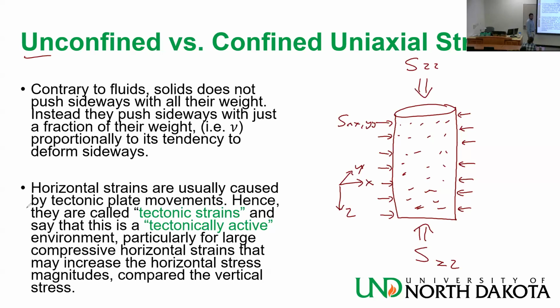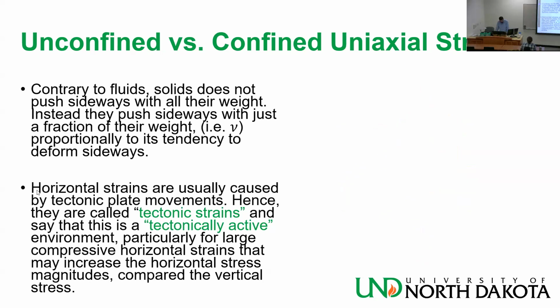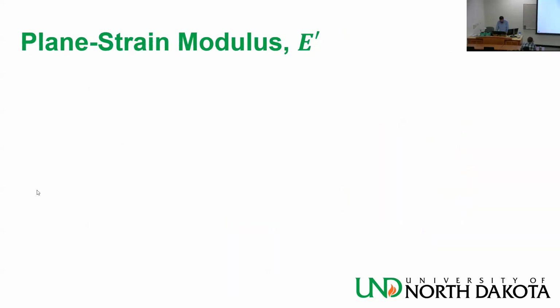Just like because we have the stiffness matrix, remember, and we go from one to another very easily. UCS is if I measure what SZZ I need to break it. That would be the UCS, but we are gonna go through it in module 3. Yeah, I remember. So increasing the confining pressure was giving more resistance to the rock to break. I should make the circle bigger. Yeah, the circle bigger.